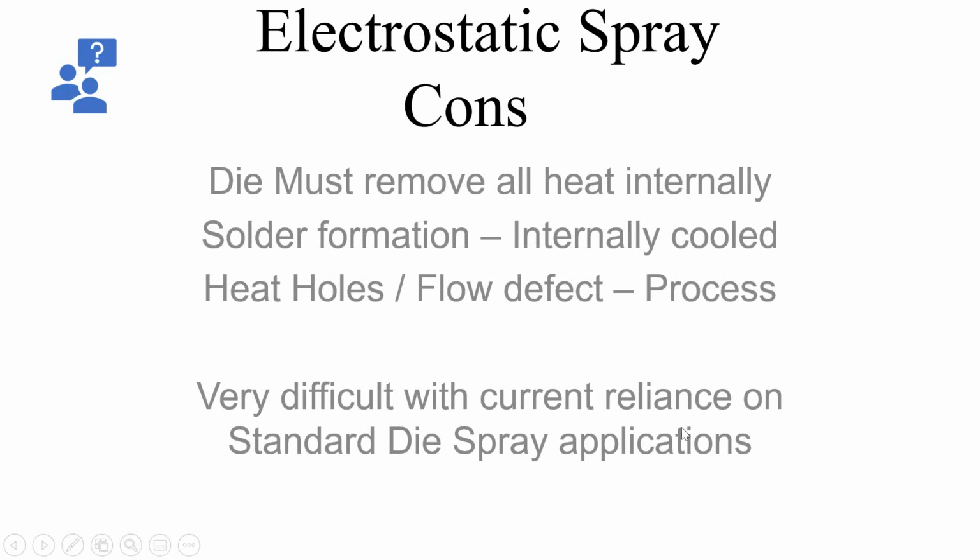So if you've got current tooling that's been designed to use water spray, sometimes it's very difficult to convert that tooling over to electrostatic. You've got to make sure you've got a good thermally balanced die, then you can use electrostatic spray.